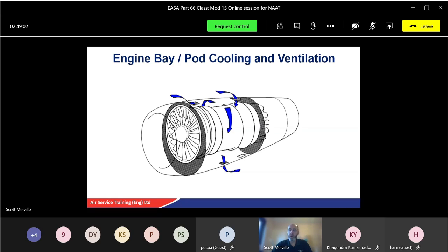Now, these grey areas here are described as fireproof bulkheads. Just in case a fire starts, we want to try and stop the fire from spreading where possible. We'll look at fire detection later on, possibly today. So we put these into little zones. Hot zones, we've got electrical fire, potential electrical fires, and obviously fumes. If we don't vent it properly, it can cause fires as well. So we separate the cool air zone of the engine, which contains fuel, hydraulic systems, etc., from the hot area of the turbine and all that. We can use differential pressures. We'll have two zones, and calibrated inlet and outlet ducts to prevent fire from spreading.